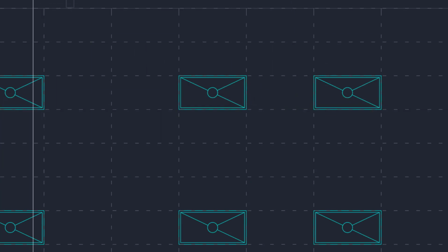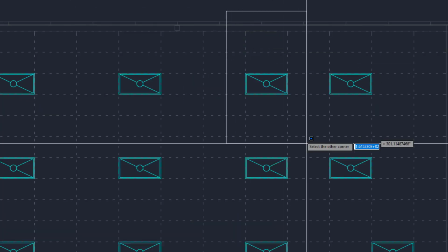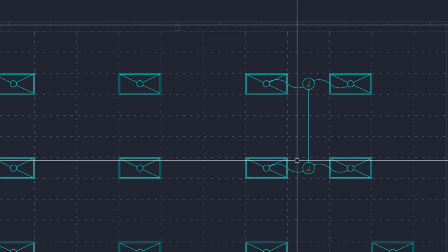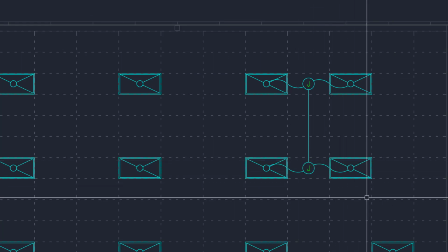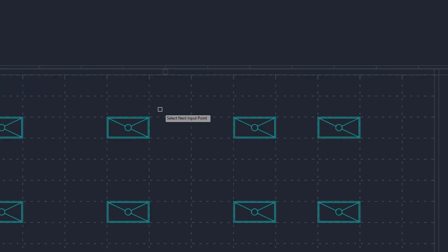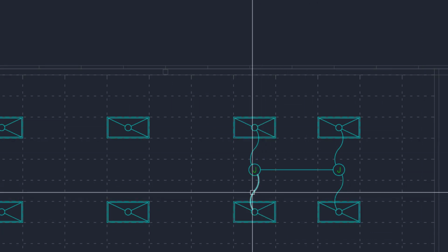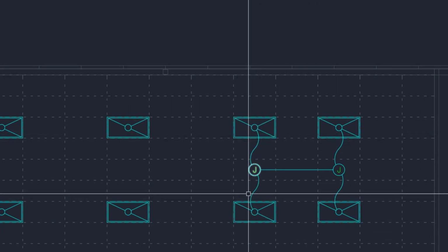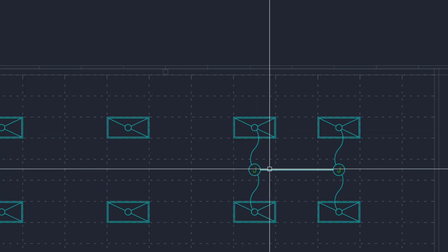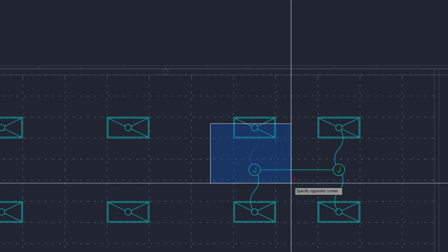I'm going to erase those, and I'm going to reset the scale to 1/8 inch equals a foot. You can select this and have it draw in for you. So there was one option. Here's another option. I'm going to undo that, pick it again, and you see it drew it the other way. So it put the junction box in and flexed up and vertically, and then the trunk cable was drawn horizontally.